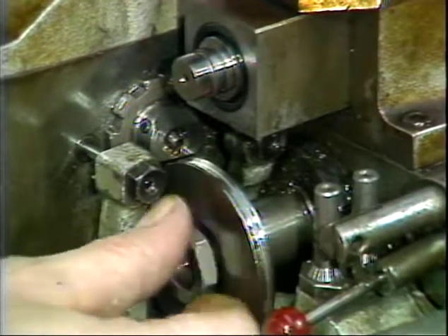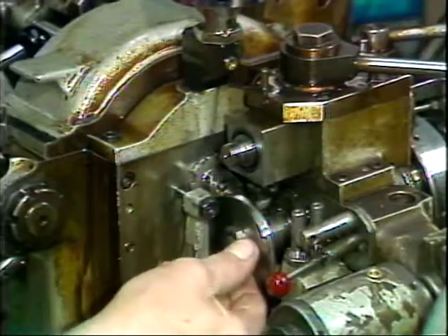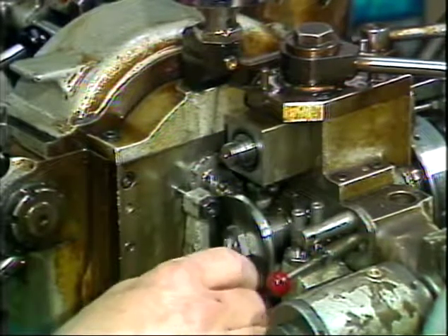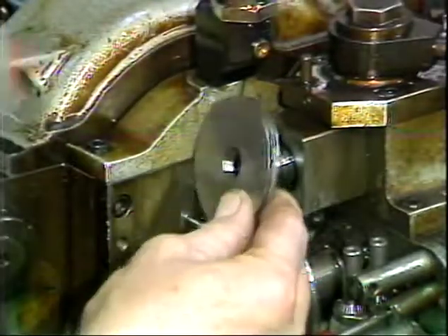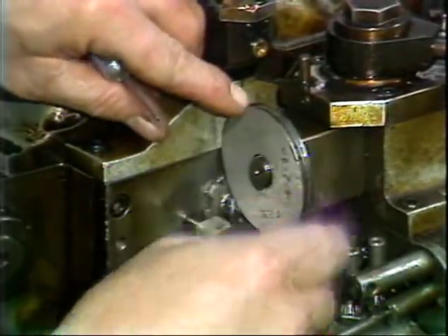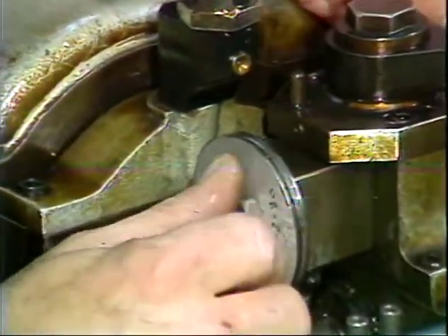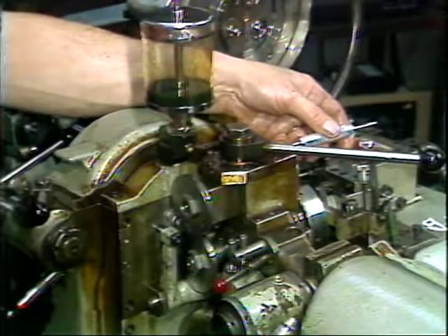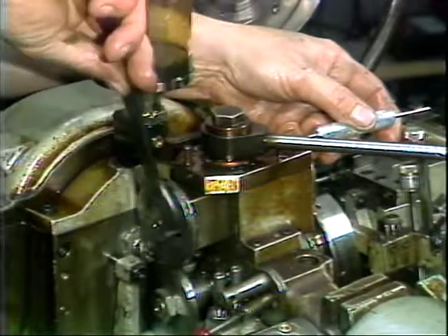Install the hold-down nut. Partially tighten the nut. Install the upper feed roll onto its shaft. Make sure the size marking of the feed roll faces out. Install the hold-down nut. Insert the pin back into the hole in the upper friction disc and into the machine frame. Tighten the upper feed roll hold-down nut.